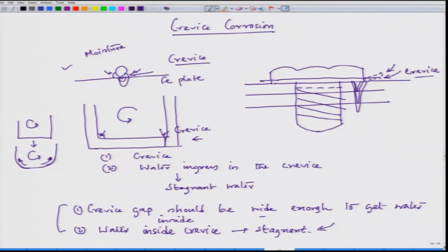corrosion. And in this case, for example, we have to first try that there should not be any crevice. So, one way is we can chop off these particular edges, which will allow this gasket not to protrude out, so that the crevice is avoided. So, this is the design factor we can think of. Now, crevice corrosion itself is a wide subject. So, we are just giving a nutshell of what the form of crevice corrosion is.